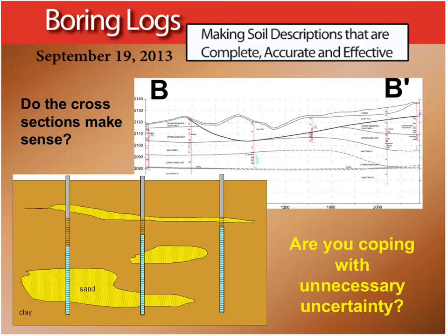Well, most of us have had at least one or all of these during our career, and when we discover one of these problems, we typically review past work such as geologic cross-sections and monitoring well locations to try to make sense of the subsurface relationships between geologic units and monitoring well screens. And sometimes we discover those correlations are fraught with uncertainty, so then we turn to the boring logs.